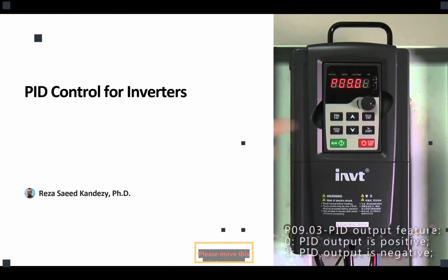No? Okay. In the previous session, we talked about grid following inverters. Basically, we said we have a category of inverters named grid following. They are a type of inverter that has to follow the grid, so they need a grid in order to tune their own parameters, and they are always following the changes on their output terminals connected to the grid.